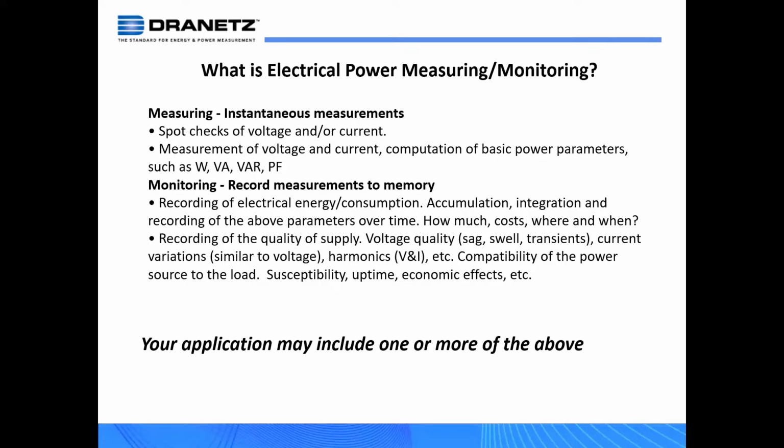And that is the opening to what I call power monitoring, whether it be power quality monitoring or just load monitoring. That opens the door to those types of applications, because when one monitors over a period of time, you're looking for changes. Do these changes coincide with things that are happening within the facility? Say I have a low voltage at 9 o'clock in the morning, when there was maybe some construction going on. So you can see how this leads into your typical power monitoring survey, PQ survey, where you're monitoring over a period of time.